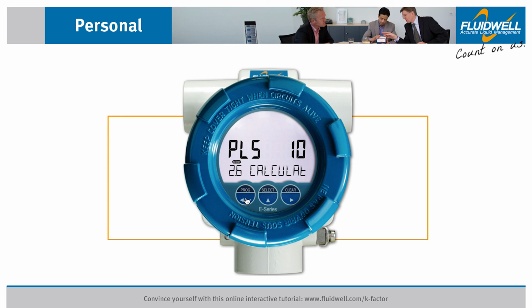The last step is to set the cutoff time. Press Select to go to Menu 2.7 Cutoff. When during the cutoff time no pulses are received, the e-series will show a 0 flow. This prevents the e-series from continuously showing the last calculated flow rate if there isn't any flow detected. Press Prog to change this setting. We select the 15.0 value. Press Prog to store this setting. The cutoff time is set to 15 seconds.